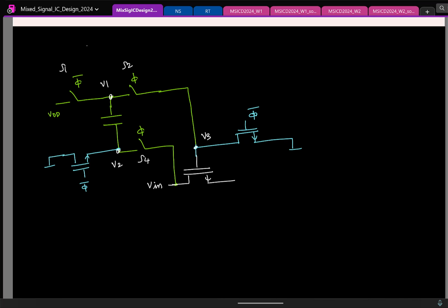Okay, you are saying source should be here. Please remember, for a transistor, source and drain are symmetric. They can be interchanged. For an NMOS, the terminal with the lower potential will be source. For a PMOS, the terminal with the higher potential will be source. That's all. It doesn't matter what I mark. But if it's bothering, I can change it. Right? Now let me copy paste it maybe. This copy works.